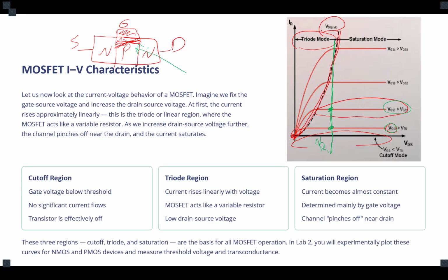As you can see, let's summarize that. Below a certain threshold of the voltage between gate and source, the middle semiconductor, either P or N, would cut the current and works as an insulator. When you apply a certain amount above that threshold between gate and source, you are polarizing that semiconductor.